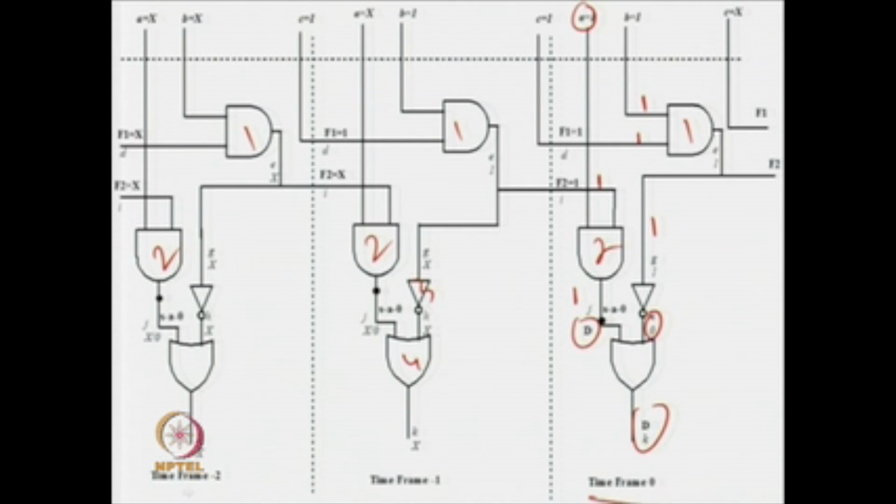So this is the last time frame. We mark it. Now, to get a 1 over here, this is in the third or 0th time step. This gate is connected to the output of the second flip flop. Okay. To get this 1 in the output of flip flop 2, one primary input can be set at the 0th time step, that is done. But the other input 1 has to come from the output of flip flop number 2.